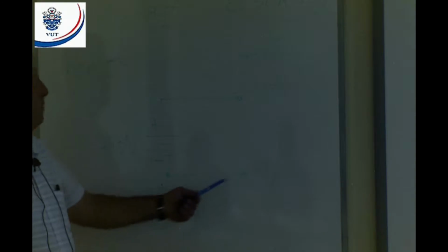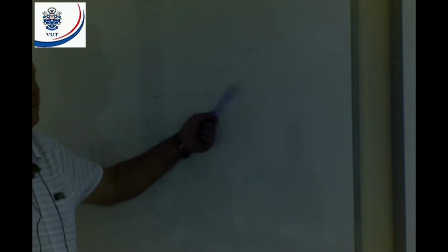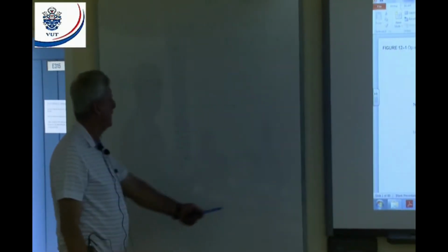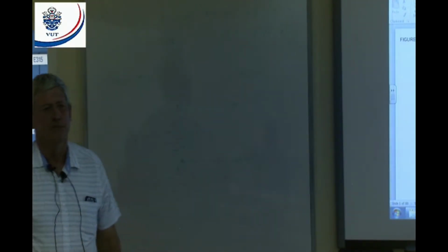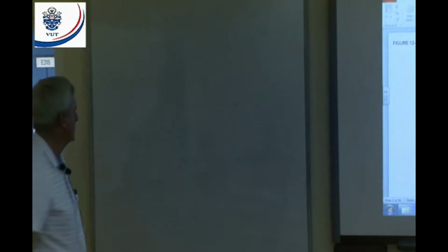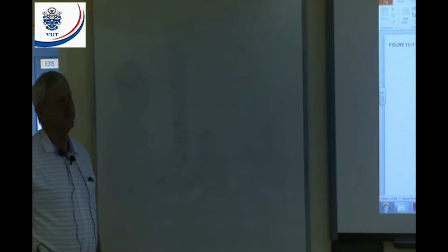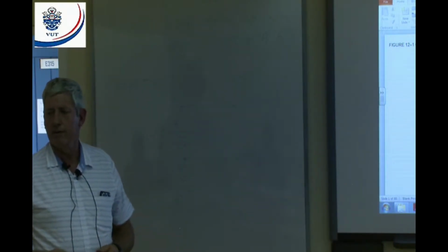That means if I put a black lead of a multimeter here, the red lead there on a voltage scale, it will give me plus 15 volts. Black lead there, red lead there will give me minus 15 volts, all right? If I put my black lead here, my red lead there, what will it give me? It will give you 30 volts, because they're in series, negative, positive, those voltages will add up. It won't give you 0 volts, it will give you 30 volts.